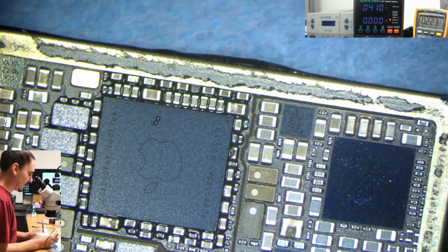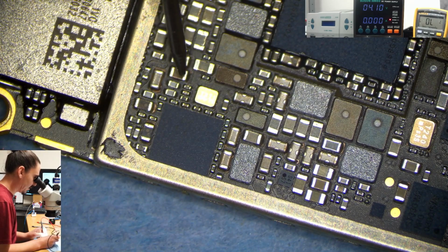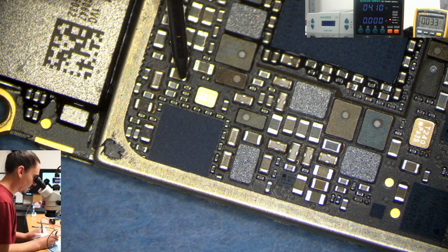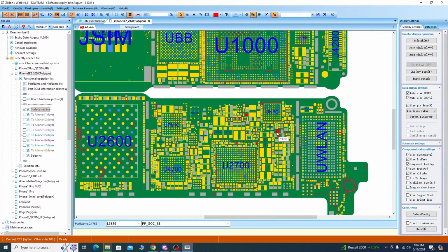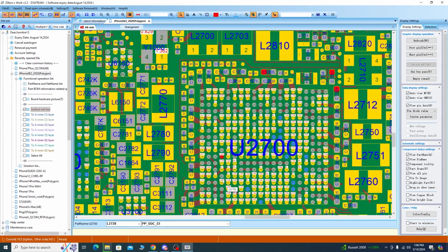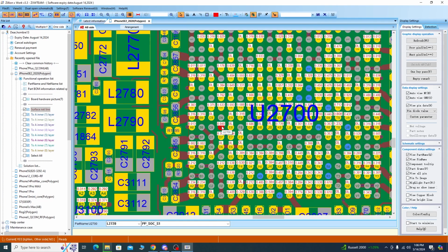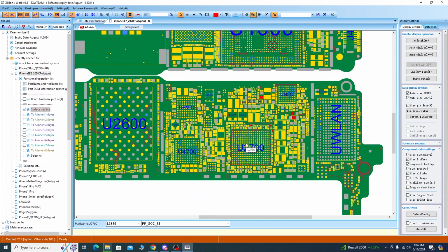And that looks good. That was my 1V1 RAM line. And then it was these two staggered capacitors was my sock line. And that's another low resistance line. I'm fairly certain that's a normal reading. And I can kind of verify that. I'll show you. So that was this one here. But if we zoom in on my PMIC here, we can see that the 0.04 is a normal reading on this line, and that's right around what I had. So I'm definitely not worried about that one.